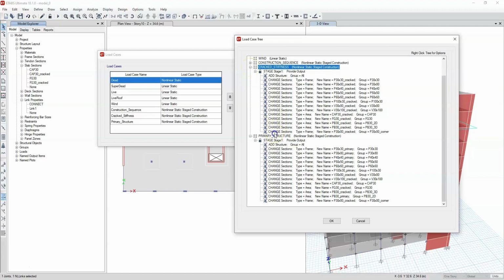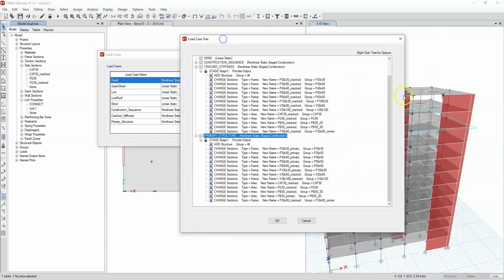The other model is the one that represents the primary structure, which is the other model necessary in this process for structural verification. Here, we contain the primary elements with 50% stiffness, but the secondary elements have a stiffness of almost 0. With the exception of some walls that have a residual stiffness that is not quite as small as almost 0 but is still significantly reduced.